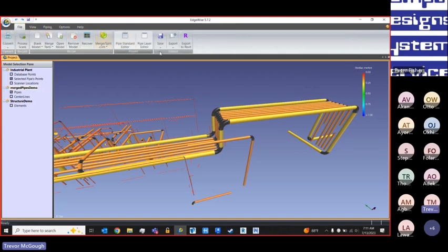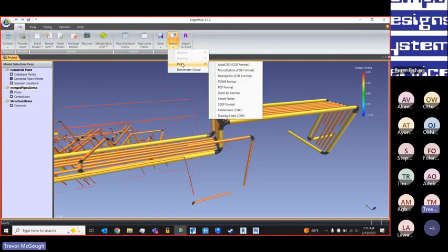Now, let's go ahead and talk a little bit about the exports. So for the exports, we have a variety of different ones. I'm going to go ahead and start from the bottom, and then we'll kind of work our way up. The last 3 are going to be kind of our primary CAD exports, and that we have STEP. STEP is going to be the 3D geometry, as well as we also have center lines and routing lines for AutoCAD. That'll be our line work.